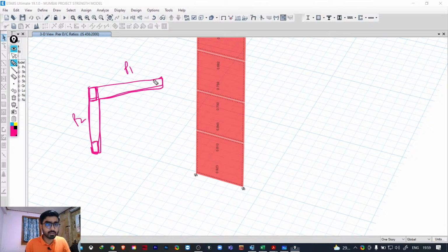This is the boundary element. Even boundary element is not always required. If it is crossing 0.2 fck, then only. If it is required, then similarly you will be designing this particular one separately, and in this particular area you will be getting, you can say, a combined result. So you will find higher reinforcement. We just have to compare PR 2 and PR 1. Wherever you are getting the higher one, you need to provide it here. C shape, T shape, whatever shape it is, you just have to break it down into single piers, right?